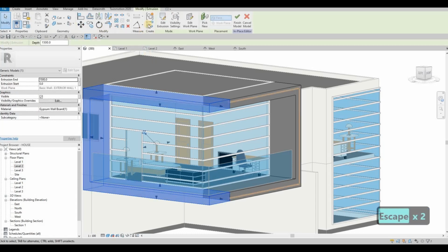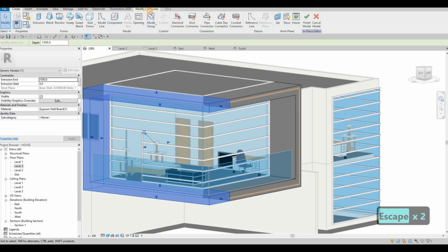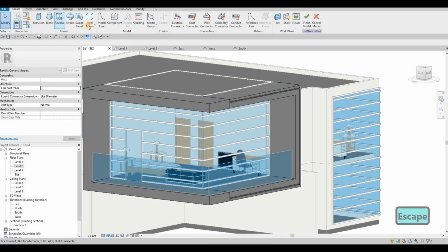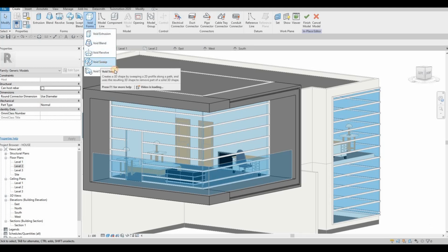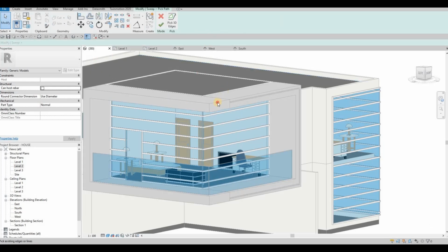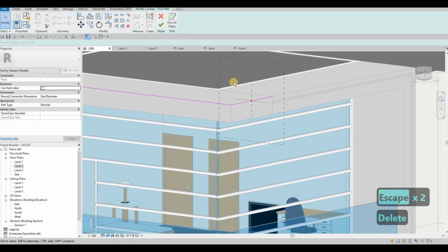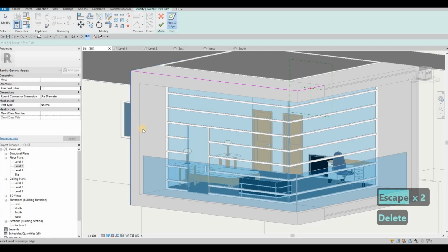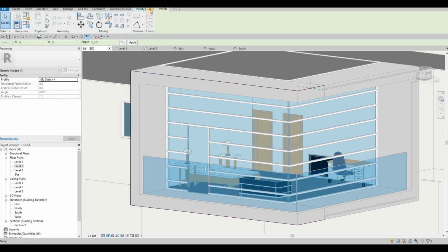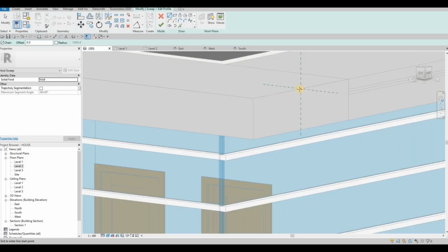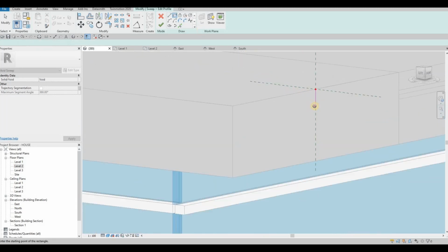So select this, so click on finish this first, select edit, and then create a void form as well. So void sweep, pick path, select this path or this path instead. Pick path on those and over right here. Select finish, go back right here and click edit profile and do the same thing first. So 100, and then here go back.